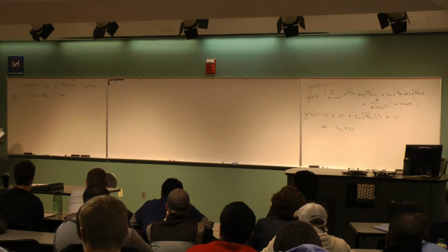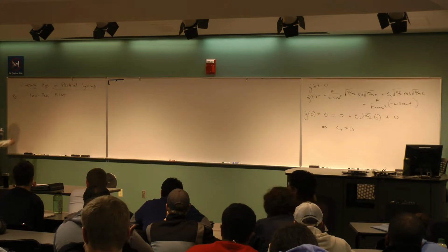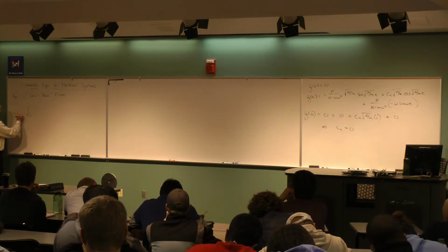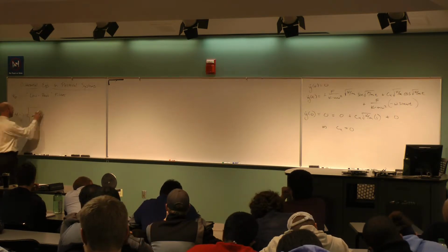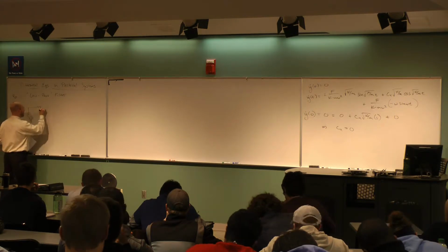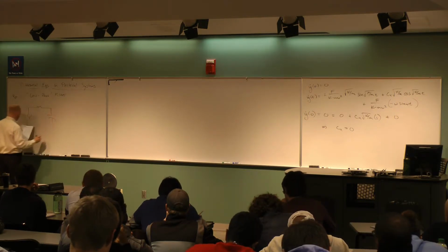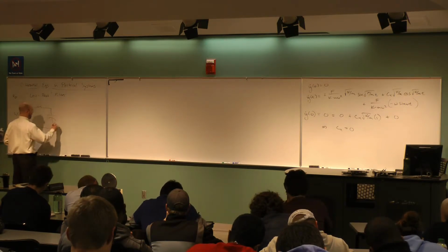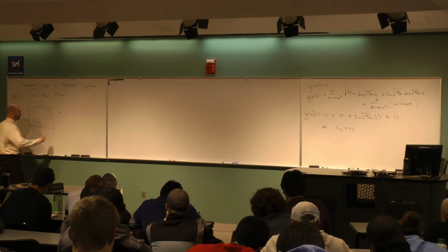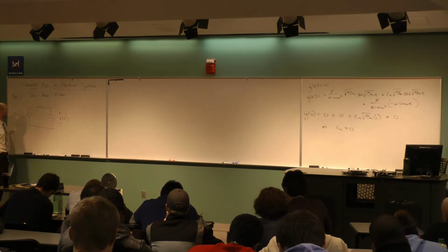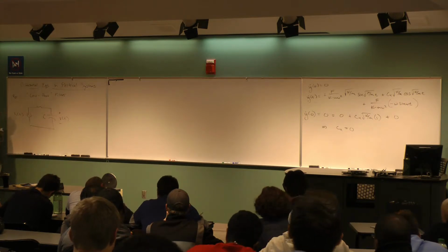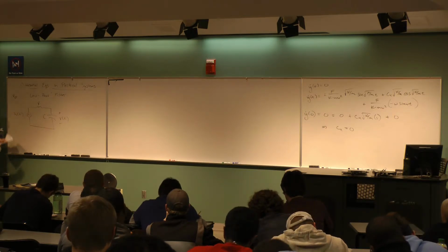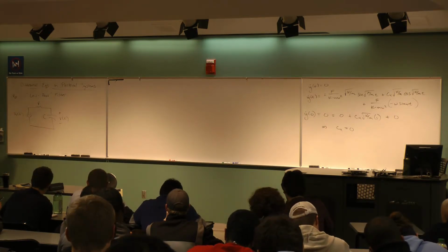So it turns out that all you need to do this is a resistor and a capacitor. Okay, so I can have over here, plus or minus, a voltage source. I'm going to call this Vs of t. That's my source voltage. If I hook it up to a resistor, and then I hook it up over here to a capacitor, then what I will have in the circuit is plus or minus an output voltage V of t across the capacitor. This is the capacitance C, this is the resistance R, and so here's the way to think about this.